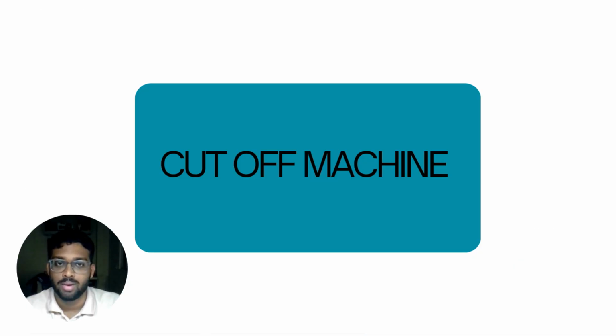Good morning, everyone. For my part of this project, I selected the cut-off machine as the area for improvement. The cut-off machine is located at our FKP workshop and it's commonly used for cutting metal materials. During our observation, we found that the cutting machine position creates ergonomic issues for users because it is placed at floor level. Therefore, our proposed improvement is to place the cut-off machine on a hydraulic jacking table so the working height can be adjusted to a more ergonomic and comfortable level for the operator.